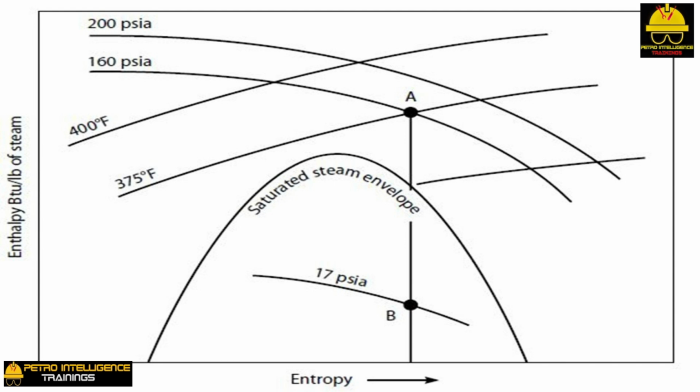5. As we shall see in the following section, most of the increase in velocity or kinetic energy of the steam does not come from the pressure of the steam, but from its enthalpy. By enthalpy, I mean both the temperature and latent heat content of the steam. Thus, as steam expands through a steam nozzle to a region of lower pressure in the turbine case, the steam cools and is partly condensed.